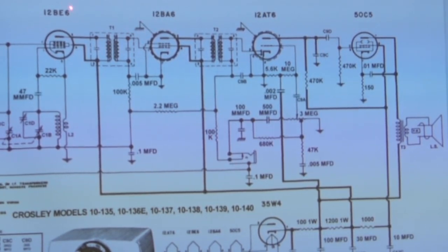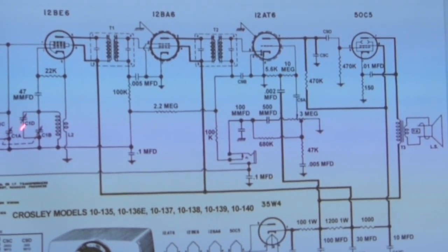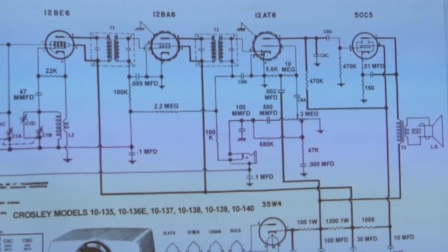Broken wire. Antenna loop could be open. Okay, we're going to assume that the input stage is working and the oscillator's running. So it's the transformer. Well, I guess you'd have to check the IF transformer. Yes, okay. So you might say either something is shorted out in the IF can or it's open. And I think in Rick's presentation, he showed us very well just how you can do that.